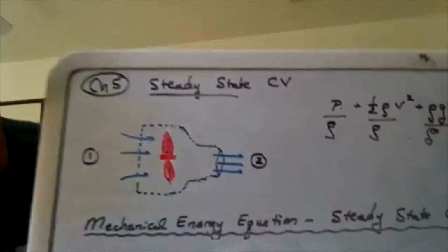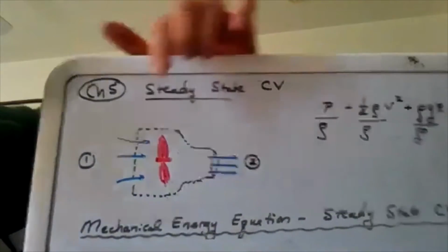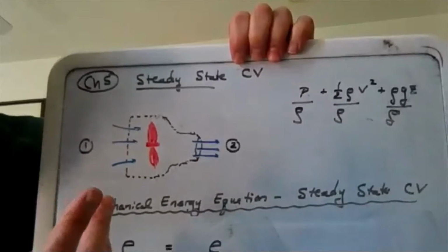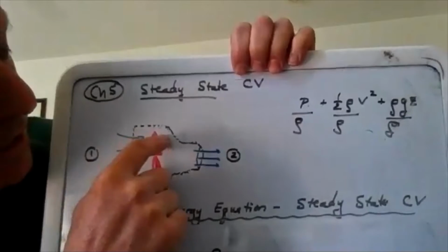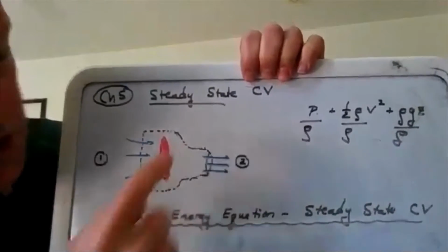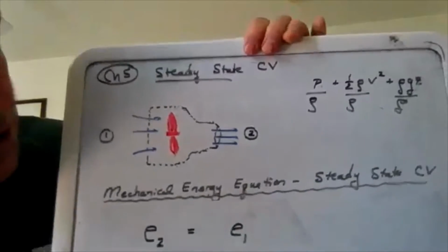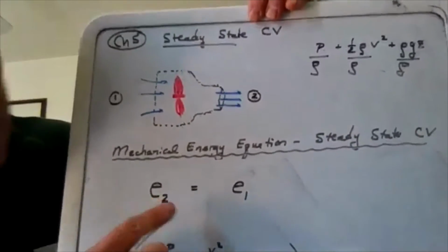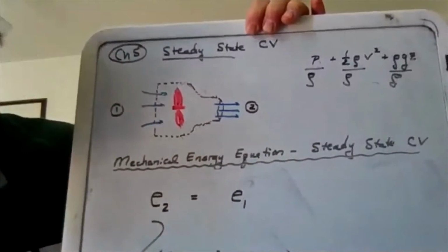In addition, you might say, hey, if you got a fan like this, you would call up the manufacturer and say, hey, you got anything better? Because you would like a fan without a lot of frictional or rubbing effects for your air. And as the air has to make this turn here, that's a pretty abrupt, quick change, and there's probably going to be some energy loss. All right, so there are two reasons why E1 wouldn't be equal to E2. First of all, the fan's going to add energy. Secondly, there are going to be frictional losses.